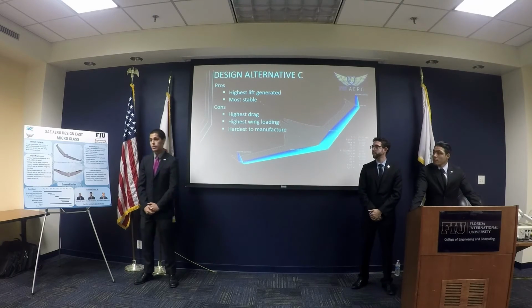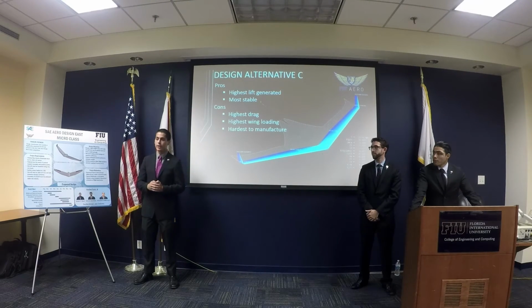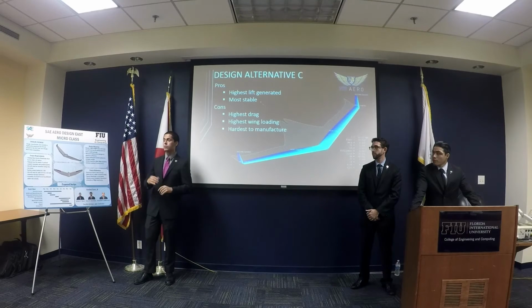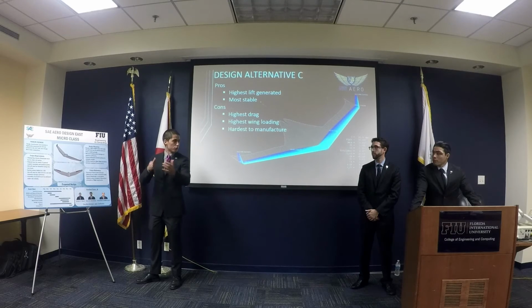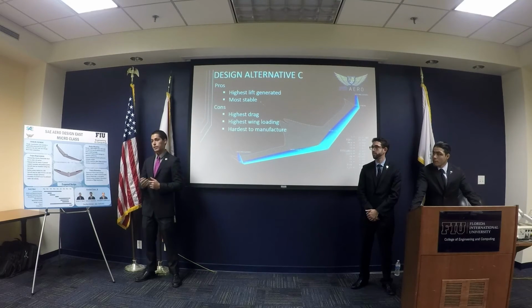It's a little more computational analysis and a little more math, but as cheesy as it sounds, we found there's a very cool factor behind the flying wing. There's something very iconic about the flying wing. And to add to what he says, we also reduce a lot of weight. Technically, we no longer need a vertical stabilizer or a horizontal stabilizer. We reduce the actual package size, since we're only focusing on the entire wingspan instead of the longitudinal axis. So we get a lot of weight reduction and size reduction.